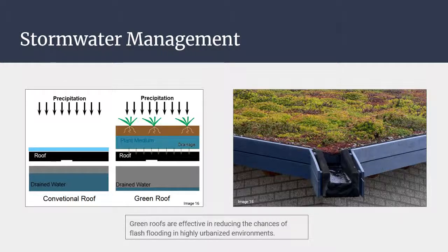When this runoff is causing flooding, it won't become treated, so pollutants such as oil, gas, chemicals, and sediment will stay in the runoff water, which could eventually hurt ecosystems, thus increasing the need for water treatment. During rain events, rain will penetrate the soil of the green roof slowly. This will help slow down the flow rate of runoff and help regulate the flow entering the sewer system, preventing it from reaching maximum capacity.